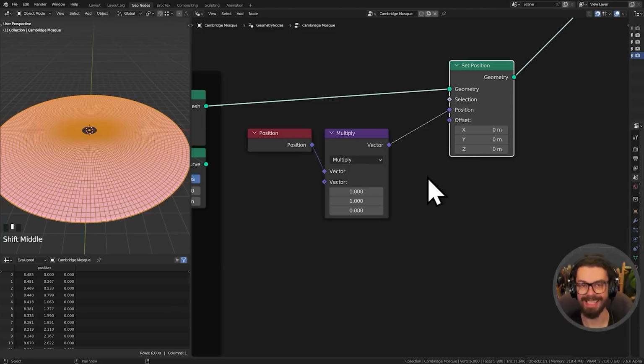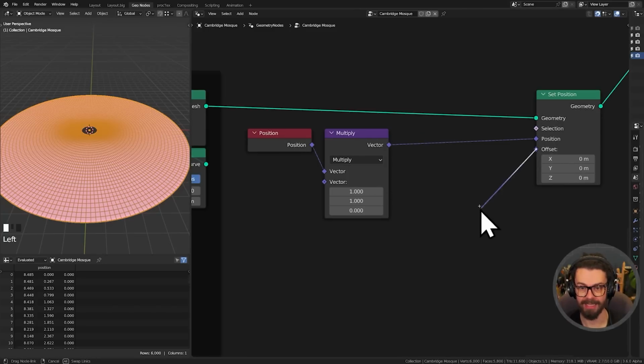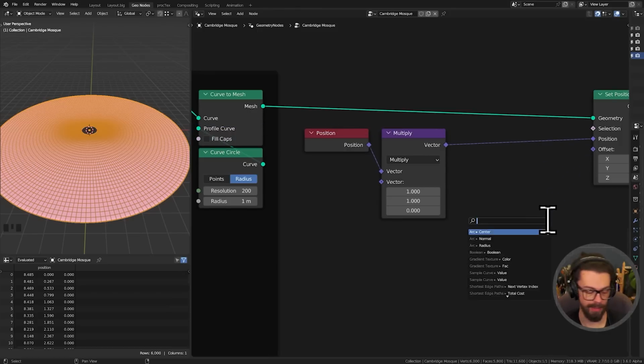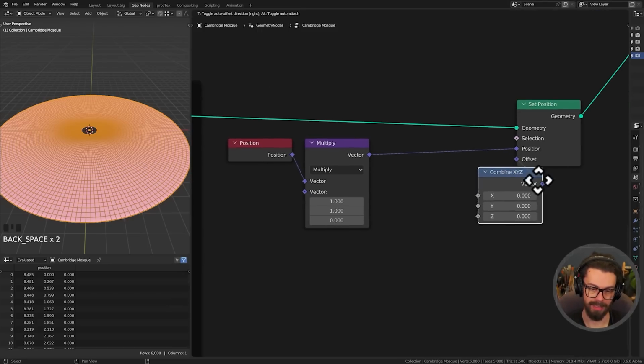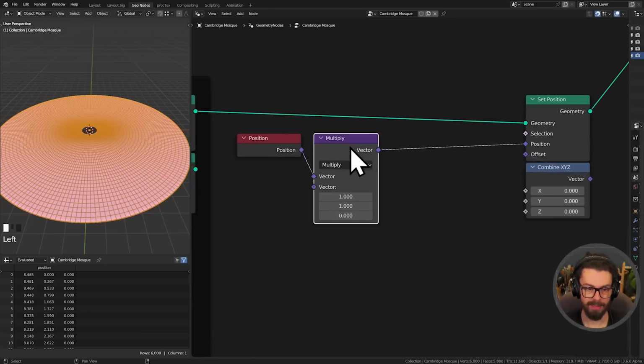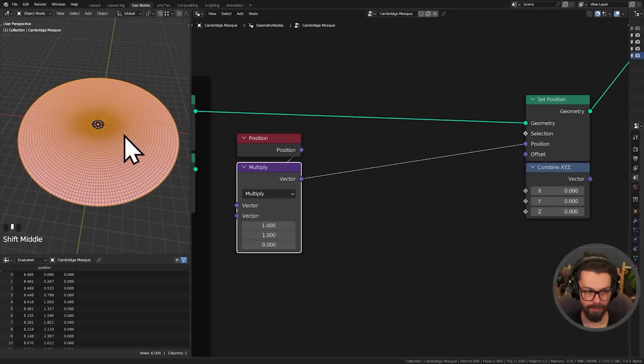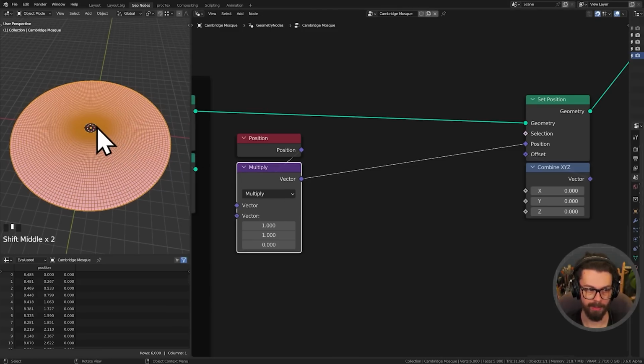We've now negated the Z-axis. We are then going to offset the Z-axis manually. So now we've got it to 0. We're going to now offset it in the Z-axis. So combine X, Y, Z is what we're going to need here. Let's find the length of the vector as we come out, because I want a gradient that is going to come out towards the edge that I can then manipulate with a float curve. So I need a 0 to 1 gradient.